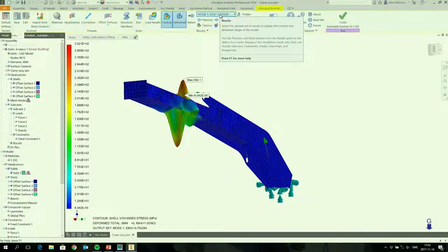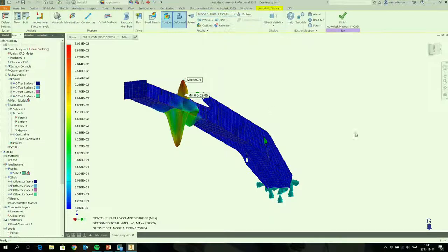And that is about the minimum you should have in this kind of simulation or design, because it is probably welded. You will have pre-stresses from welding that might give, or probably will give, some compression stresses that will initiate buckling, and it will probably have some predefined buckling. So you need to have a bit of a margin.